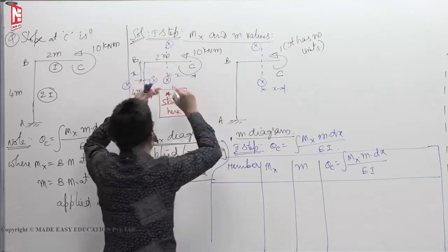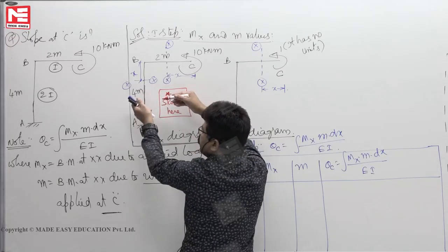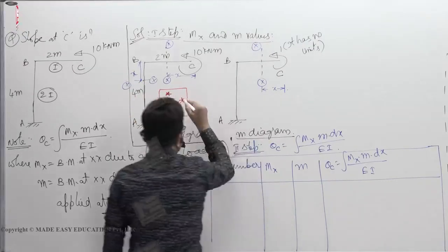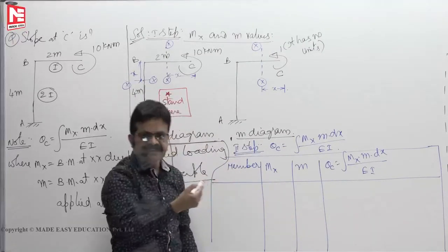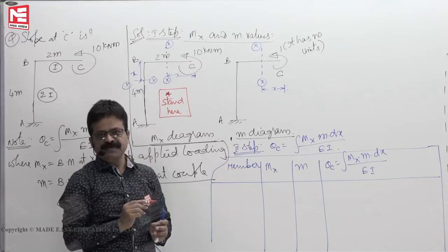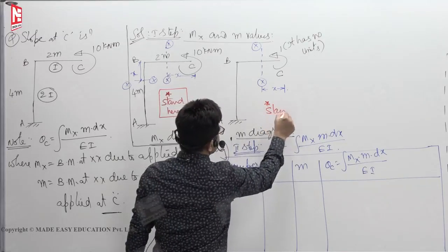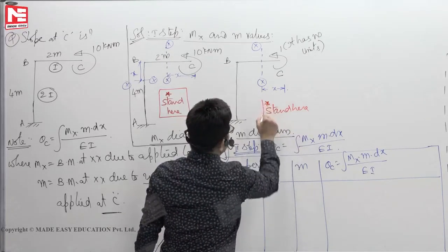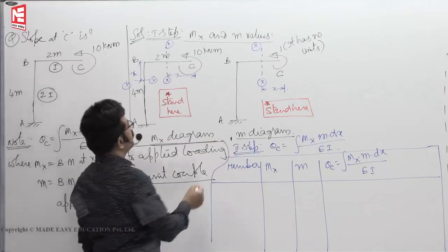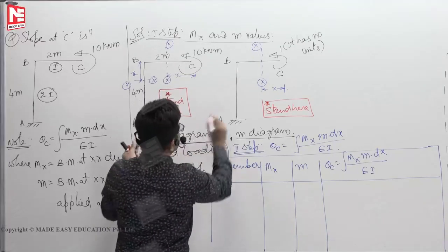Same thing if you want to find the bending moment here to detect whether it is sagging or hogging, stand here, look this side. Okay, always you stand inside the frame, and if you take sagging or hogging, it will tally with our already learned sign conventions for bending moment. Here also same thing. You stand here and see whether moment is producing sagging bending moment or hogging bending moment. Okay. Now when you take a section XX here, here also same way you have to take section XX.